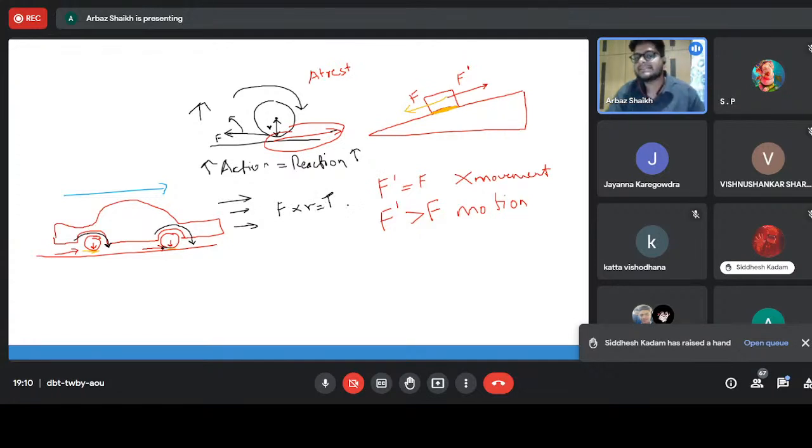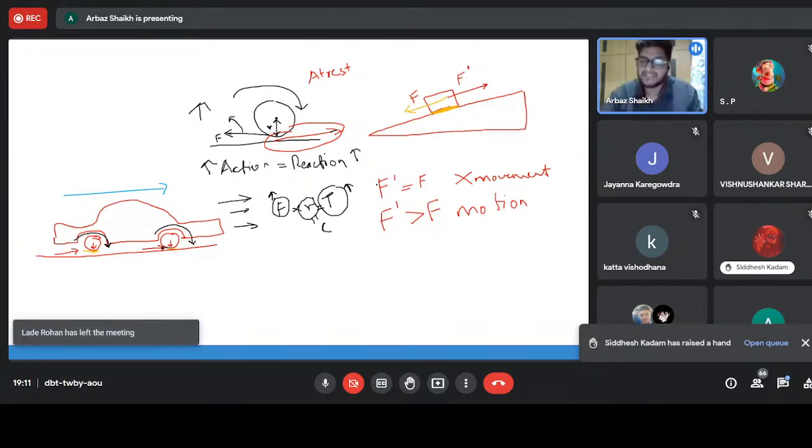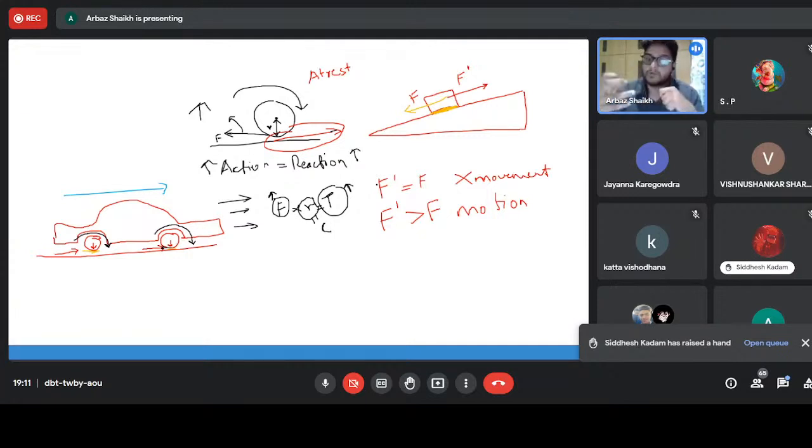Now, there is again some amount of torque we need to apply, or some amount of force we need to apply to move forward, correct? That will be the action force. Now, while you're on the vehicle, you cannot change this R, so this becomes constant, right? If you want to increase this force, you'll have to increase the torque, correct? And when you're sitting inside a car, the first, second, third gear, or mostly the first gear, will give you the maximum torque. That is why when you're starting a vehicle or when you're going up a slope, you always keep your vehicle at lower gear, because you need to get more torque so that you can get more action force. Is that clear to everybody?